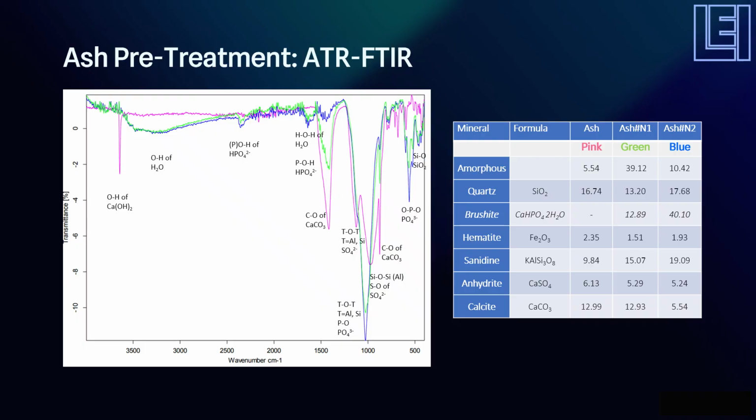Here we see the FTIR analysis of ash before and after treatment. We see that after ash treatment, there is no longer OH stretching vibration coming from portlandite.